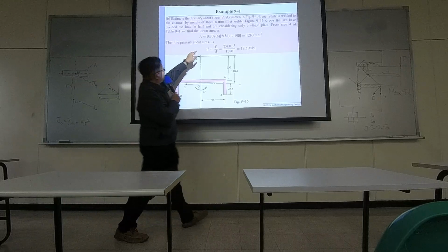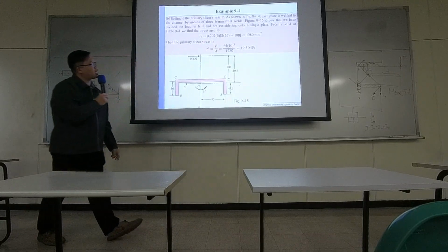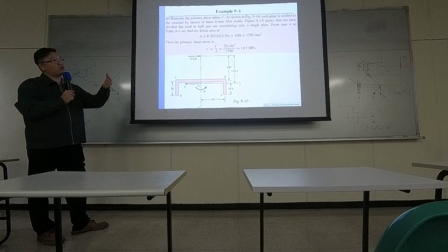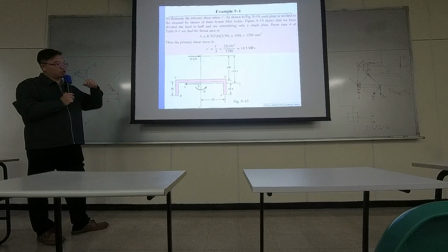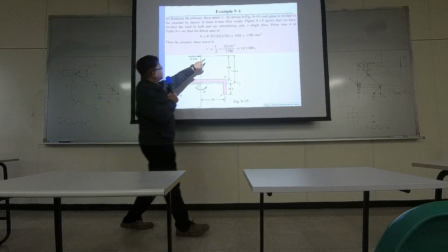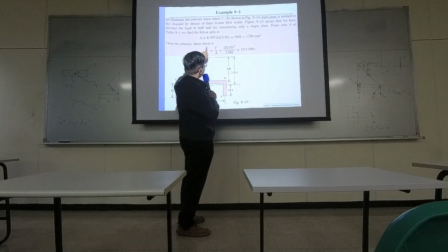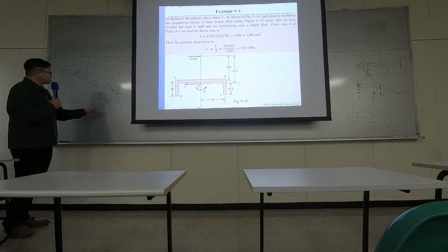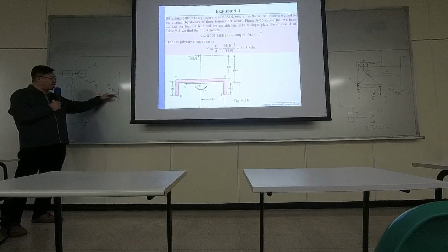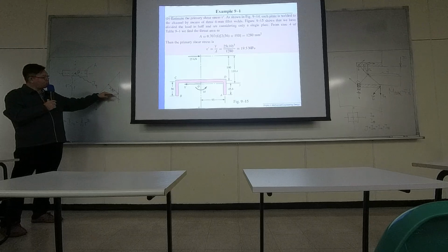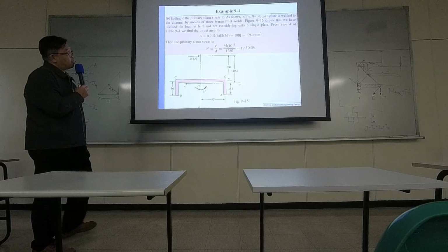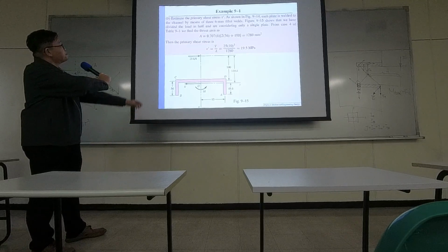So that's why there is 0.707 times that area. A shorter throat is going to lead to greater shear, greater stress, because smaller area means greater shear. That makes sense, because the original geometry on the edge is not the most critical area. The most critical area is on the throat, where you have the smallest effective area for stress.